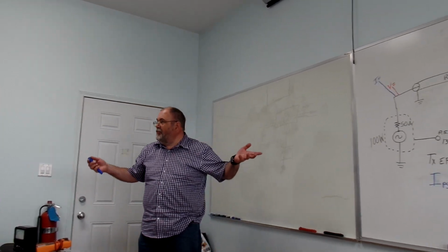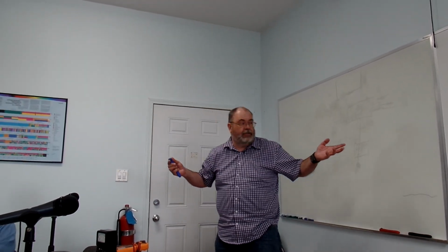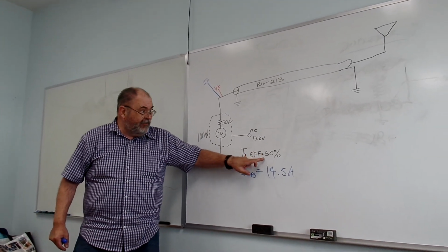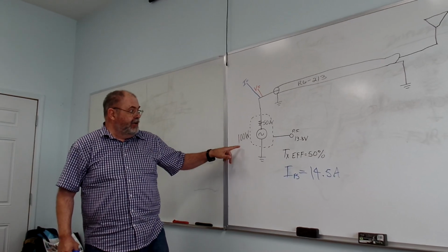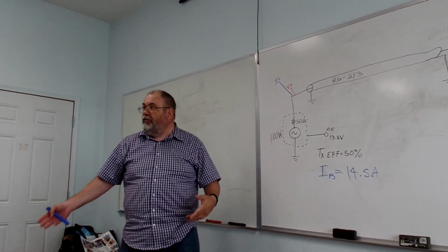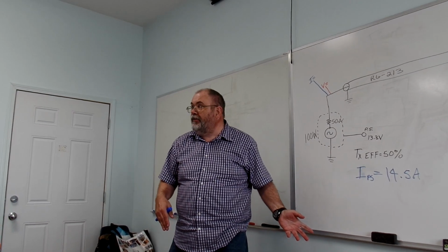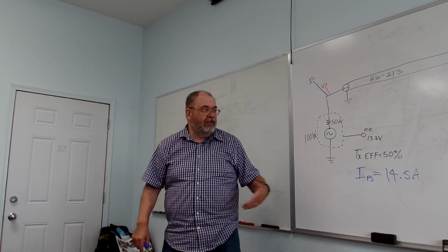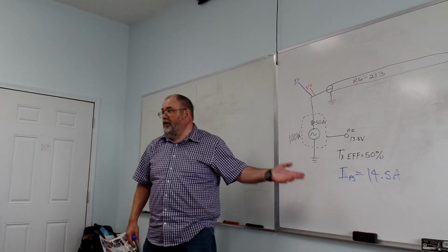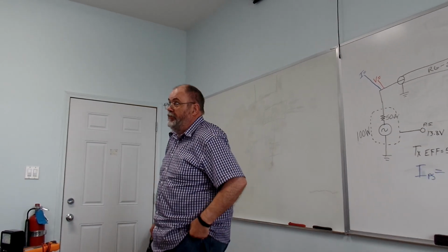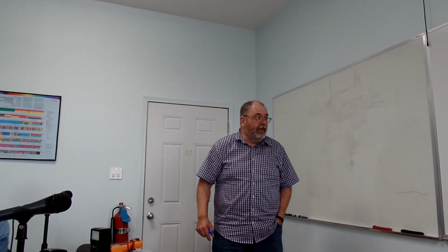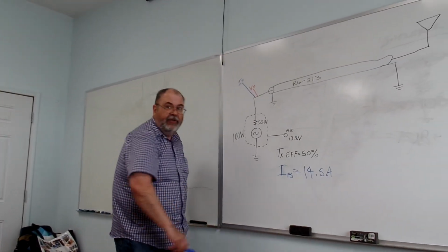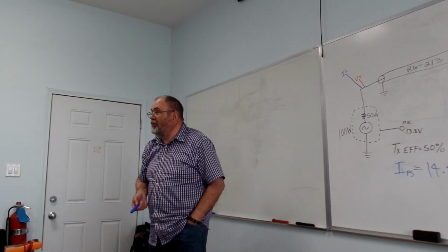So that was just a reasonably easy Ohm's law calculation. The thing I threw at you was the 50% efficiency, so you had to realize that if you put 100 watts into a transmitter, you don't get 100 watts out. Modern transmitters are probably 75 to 80% efficient. Older ones, 50%. And real old ones, 20% efficient. They took lots of power. So in other words, your 13.8 volt power supply better be able to deliver about 15 amps or more to safely run your 100-watt HF rig.